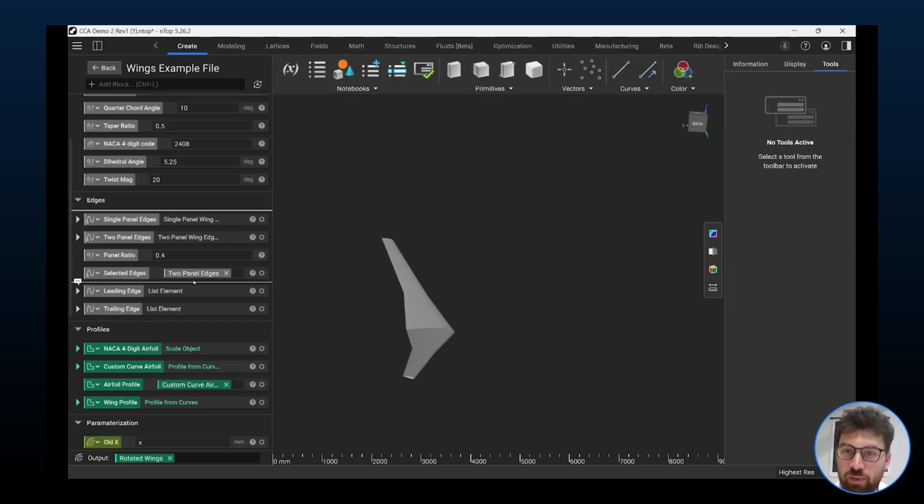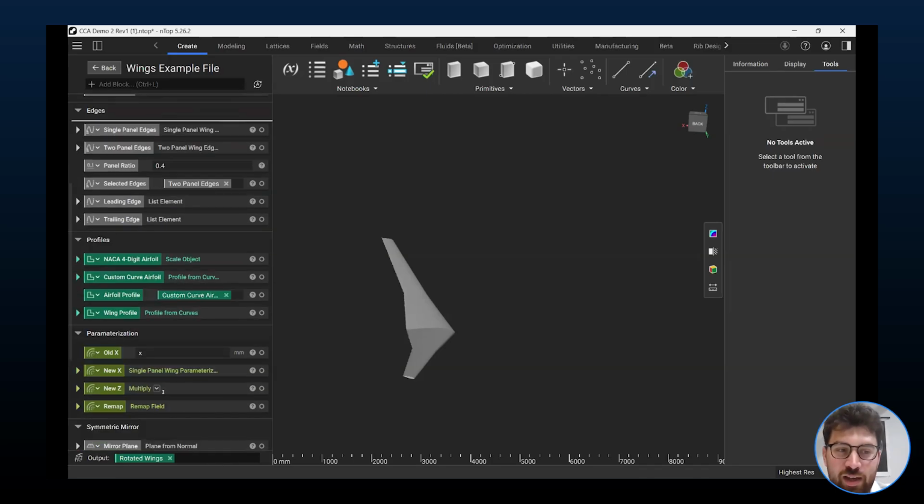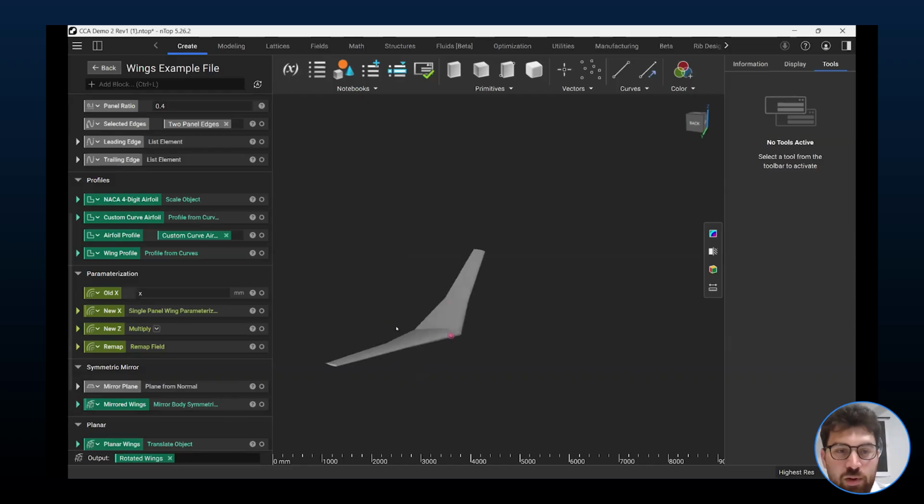So really throughout this workflow, we can understand how we can level up these traditional explicit components that we start with, such as points and edges. We can make these into 2D profiles inside of nTop, and then we can parameterize these across a wing to give us really unique volumetric operations extremely easily. And you can also see as I've changed all of these points, our workflow has been intact the entire time because of, again, the visual programming interface that we have here with nTop rather than that historical based modeling tree.